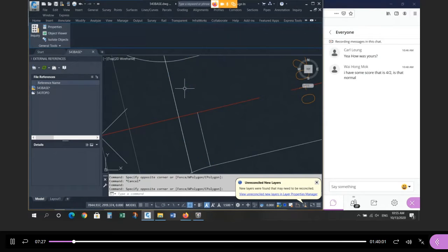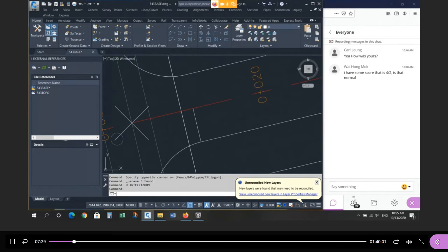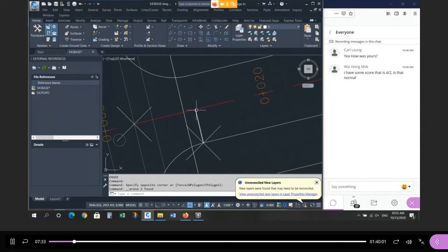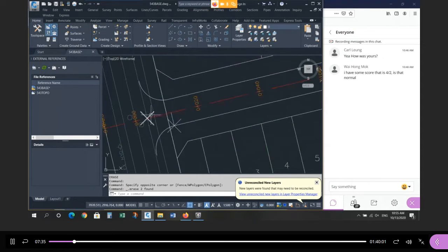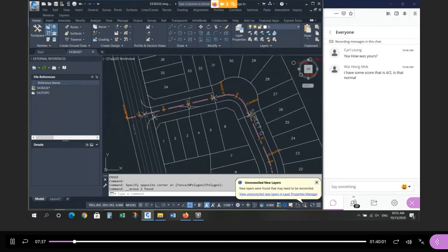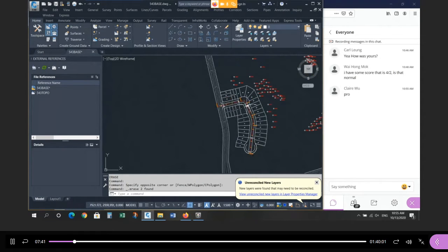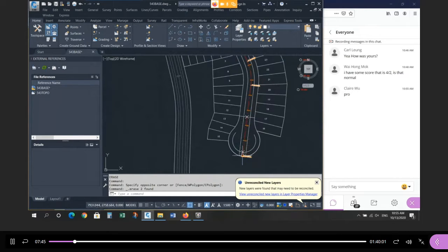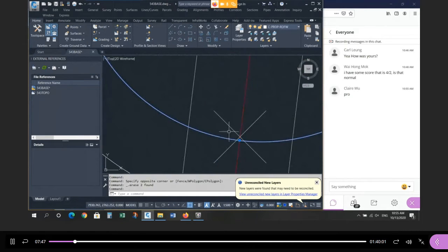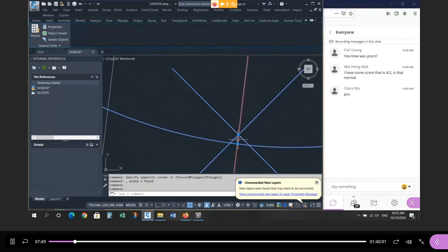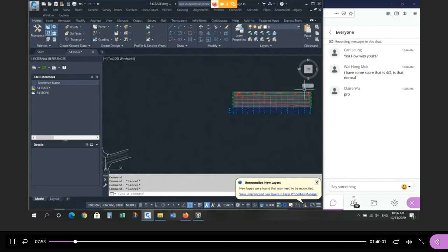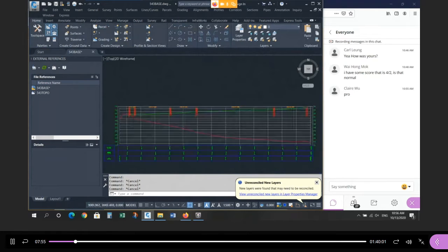So I would ignore this. Okay, I would ignore that one. So that's the station for my low point, right? So edge of asphalt down 0.5%, then it's all positive. Up 0.5%, up 1.5, up 0.5% all the way to here, and then up 1.5 all the way to not the gutter, but the edge of asphalt. That distance is 0.3. So I project those points, I connect the dots, and once I have the station values,